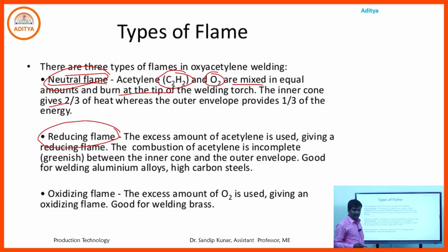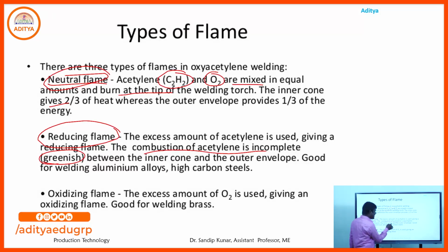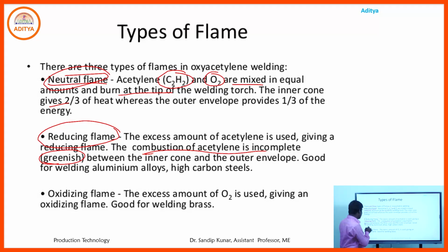The combustion of the acetylene gas is incomplete, and it shows a greenish type color between the inner cone and outer envelope.